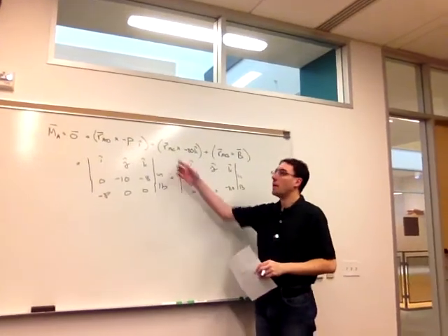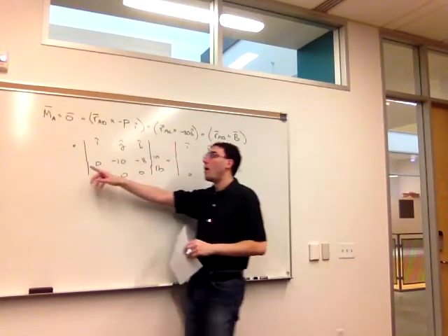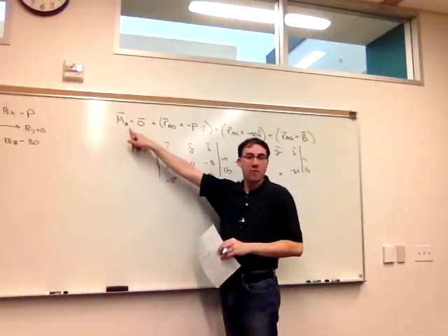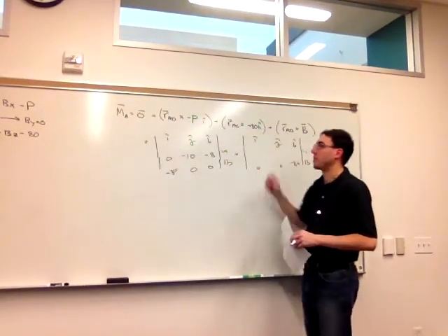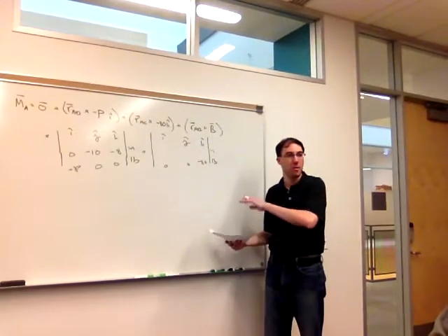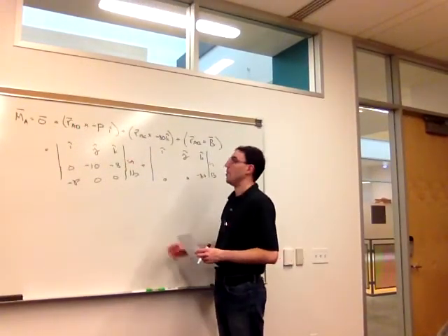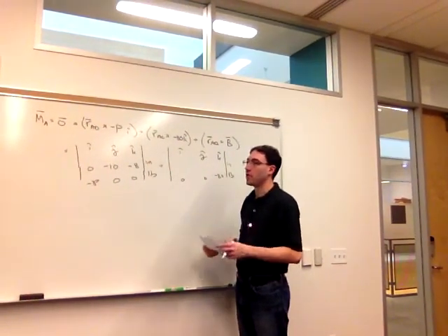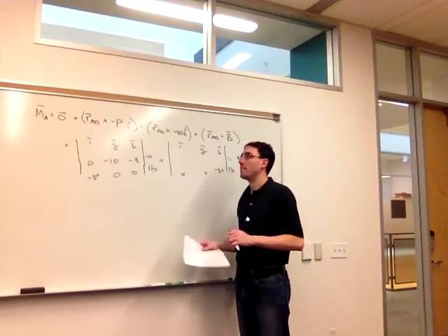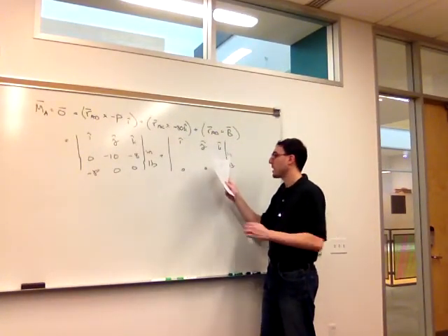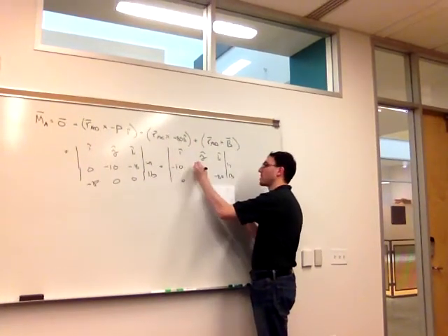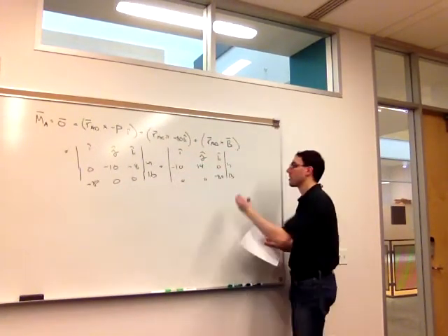And RAC, just taking a step back, also taking the moment about A rather than B is good, because A is the origin, so the position vectors are just easier to find than if we took the moment about B. So with that, combined with the 2 forces at A, moment about A is a little bit easier. For RAC, we get negative 10, 14, 0.